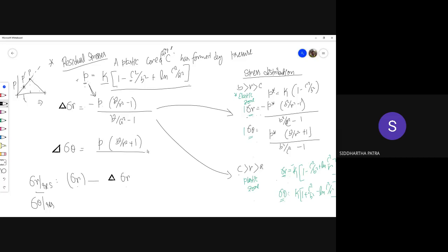If that entire pressure could be applied within the limits of elasticity, what would be the stress distribution that is being unloaded? So this should be subtracted from each zone to get the expressions for the residual stresses. Substitute the expression for P, then you have the complete expression.